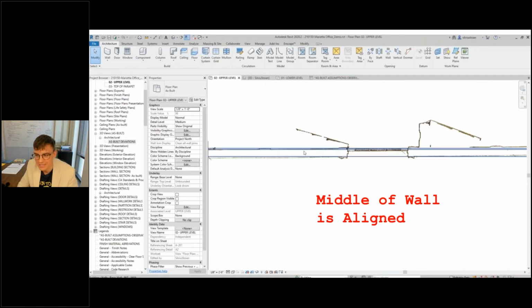Sometimes this is a good strategy, but you have to be thoughtful about it. If the model will be used for, say, logistics planning, you may want to err on the side of giving the occupants the perception of having less space than they actually have, so that you don't get any calls complaining afterwards. And if you're instead modeling a beam that's sagging or deflecting, you might want to align the beam with the supports and the connections rather than just averaging it.